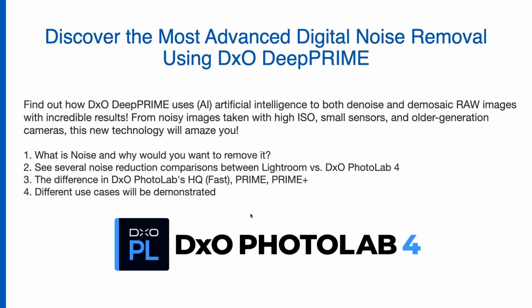But that digital sensor, that sensor that's made up of all these photosites, can capture light at what we'll call a native ISO, its native sensitivity. And depending on your camera, that native sensitivity could be higher or lower. Some cameras have a native sensitivity of 100 ISO, some have 400 ISO. If you get into the world of video and film, then you'll find that you can even get sensors that have dual native ISOs, meaning that the sensor looks equally good at, let's say, 400 ISO and 2500 ISO. It's simply how those photosites are tuned.